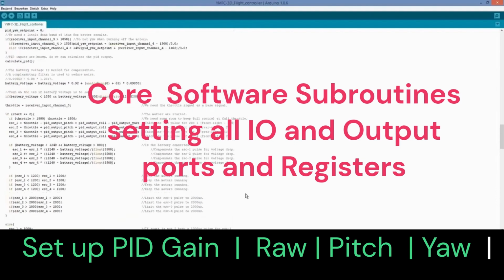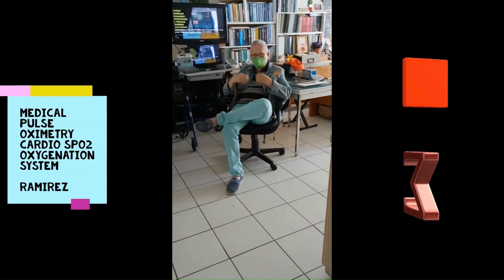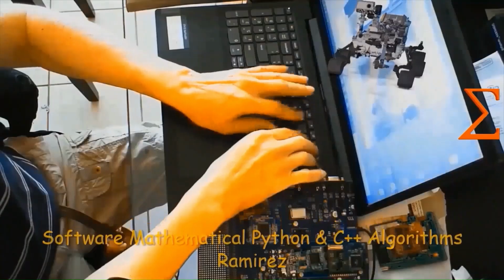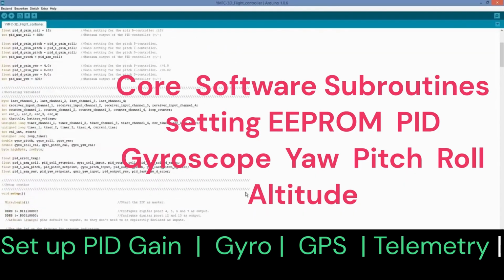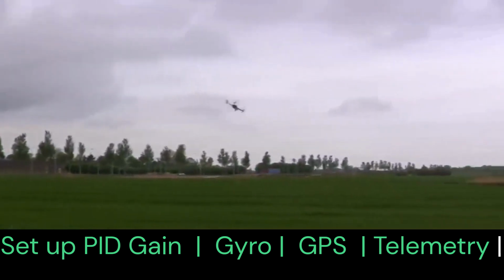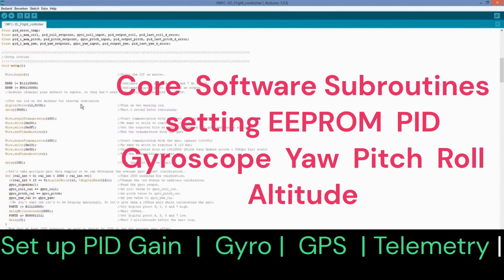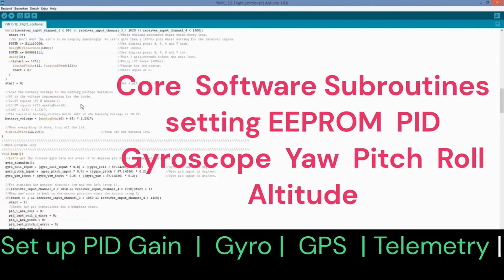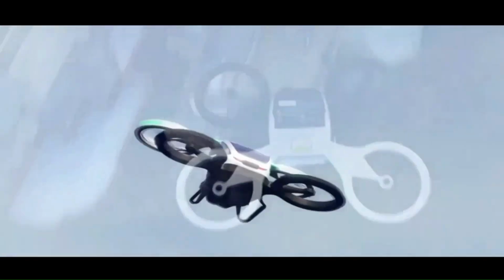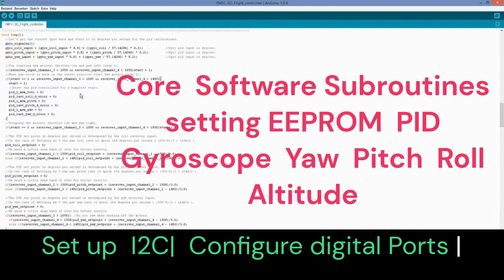Next, declare all global variables for channel 1, channel 2, channel 3, and channel 4 in the EEPROM data, high byte and low byte. Now let's set serial to 57600. Store the gyro address in the variable. Set the I2C clock speed to 400 kHz and start the I2C as master.